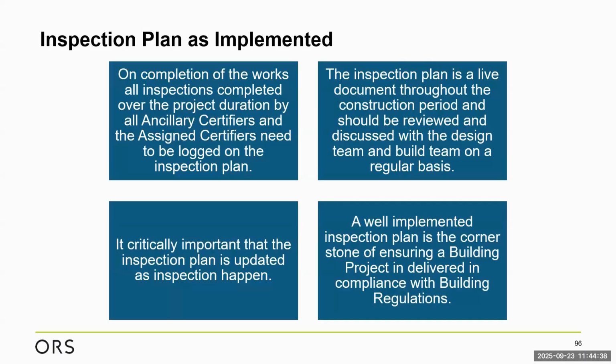A well-implemented inspection plan is the cornerstone of ensuring a building project is delivered in compliance with the building regulations. I really believe that if you put time into managing the inspection plan and everyone buys into it, it guides everything else. It guides our inspections. It guides the issues log. In parallel with that, we have our schedule of documents that we're also tracking all the way through the project.